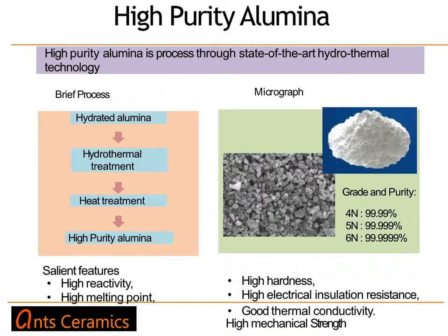High purity aluminas have very high reactivity, very high melting temperature, high hardness, extremely high electrical insulation resistance, and very good thermal conductivity. So these are used in LED applications, semiconductor applications, phosphors, automotive sensors, lithium ion batteries, and many other industrial applications like seals and many other technical ceramic applications. That is why these are in very high demand at present.